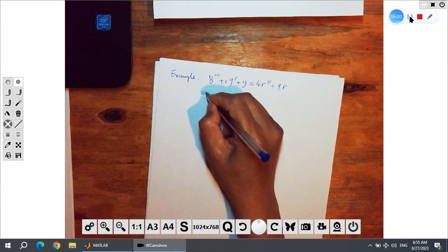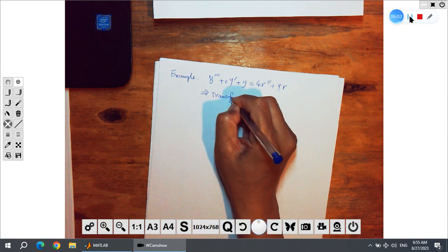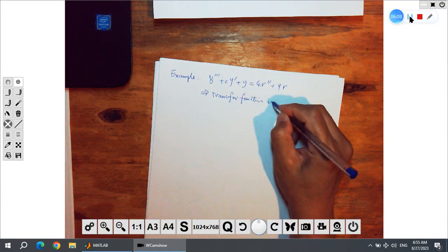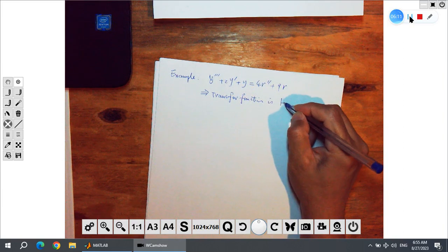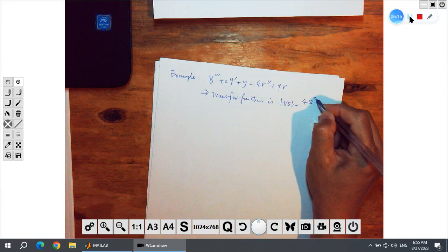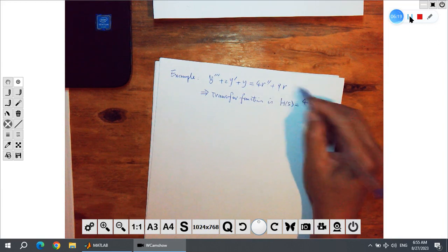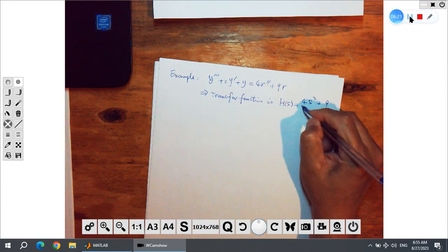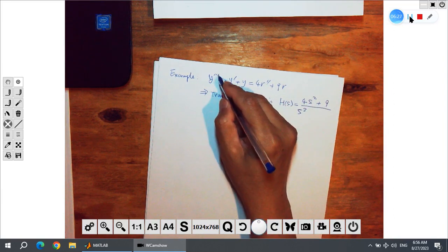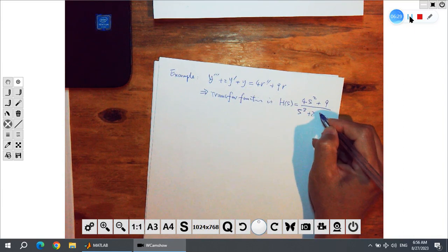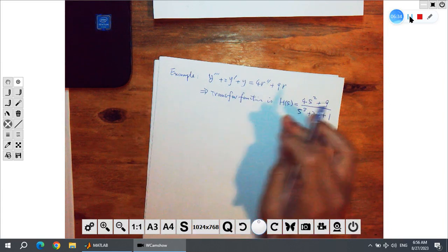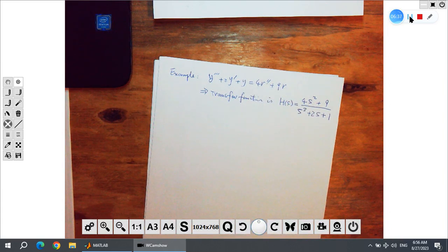Then we have the transfer function, I still use H. This is 4 with s squared, because it is the second derivative, plus 9, just 9, no derivative, right? And here is s cubed, because it is the third derivative, plus 2s, plus 1. That's it. Now you give different inputs, multiply by these, and you can have Y of s.